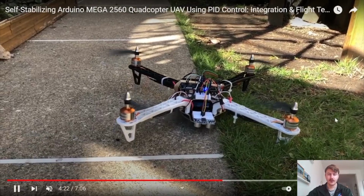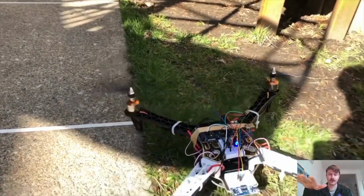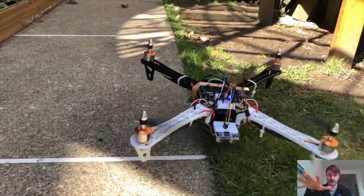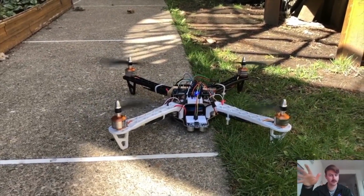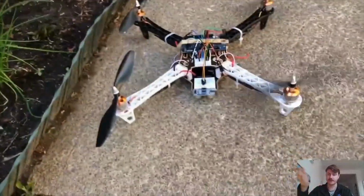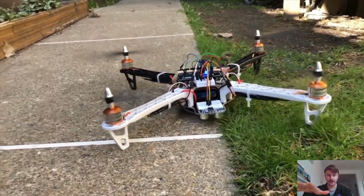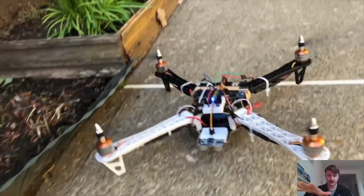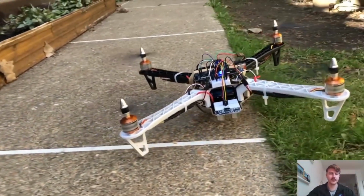But notice there are multiple corrections of body position throughout flight. So the control algorithm is working. It's just the trim was off. It was a little too far forward. This one, same thing. I readjusted the trim and you see it take off. A couple control corrective actions. There's another couple of them. It's relatively stable, but as the trim is off, it's drifting to the right.